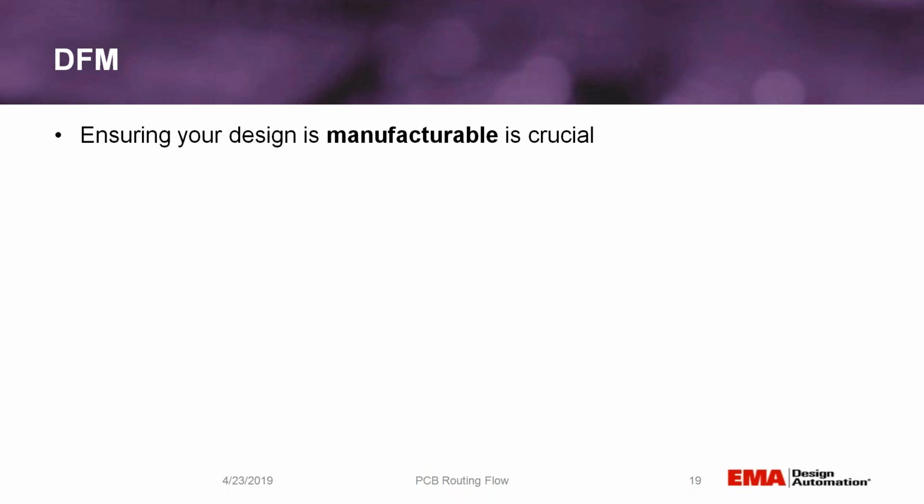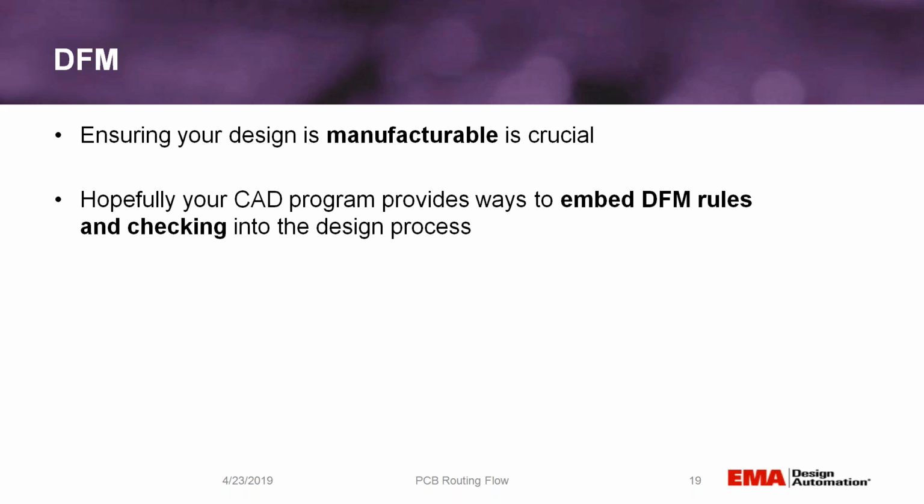Another very important thing is DFM. So you want to make sure that your design's manufacturable. And hopefully, your CAD tool can provide you a way to embed DFM rules and checking right into the design process. So some time ago, when we would generate our design data, we would send it off to our fabricator, and they would run it through Valor or some tool like that, and they would analyze the design, and then they would come back with a list of manufacturing defects.